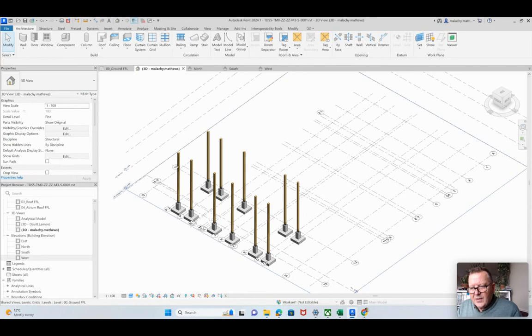So I'm going to slope from here down to there. So I'll probably have a timber beam running the whole way across here, all the way around, something like that, which will help in terms of the structure. And then in between, I'm going to do a beam system with maybe 225 by 50 joists. And I think I'd like to have those joists exposed in the atrium as well. So on top of that, then I'm going to create an insulated roof system, and I'm going to probably go for a zinc finish on this as well. So that's my thinking. Yours might be different to mine.